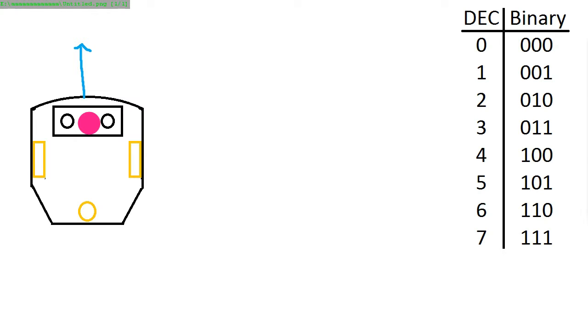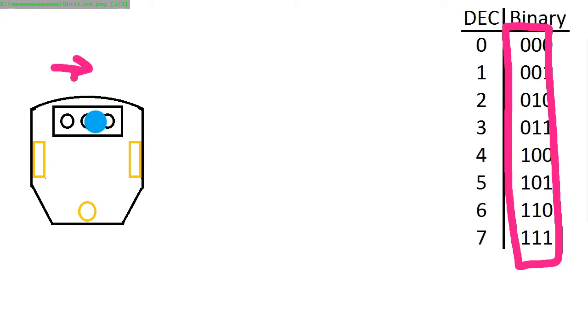Okay. Should it detect a line that spans two sensors, this basically means that the robot is busy drifting off the line. It is drifting towards that way. So it has to be pushed that same way in order to bring it back onto the line again. Right, so I'm not going to discuss now how I get these values. This will be for a future video.